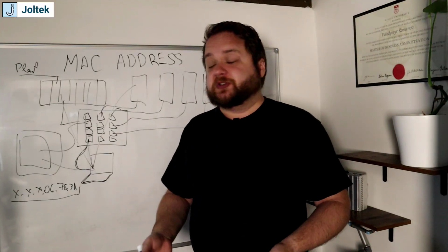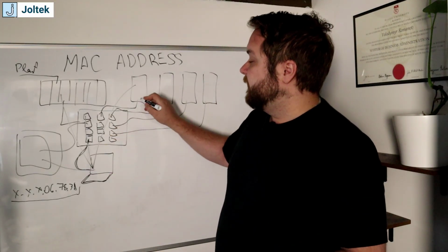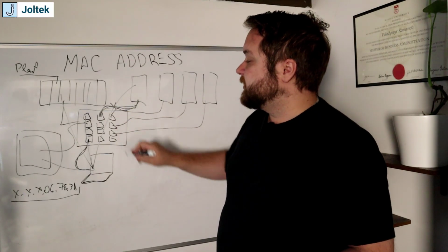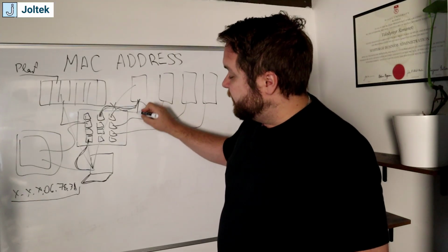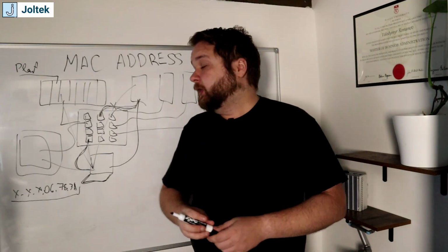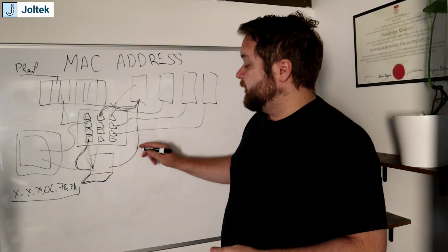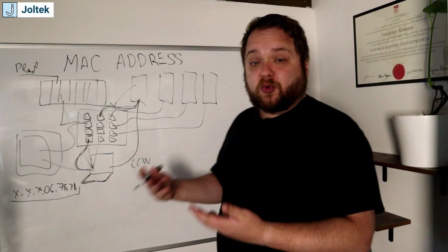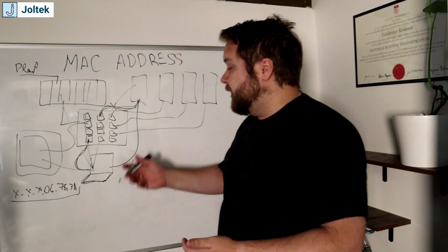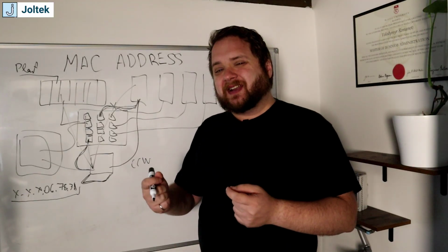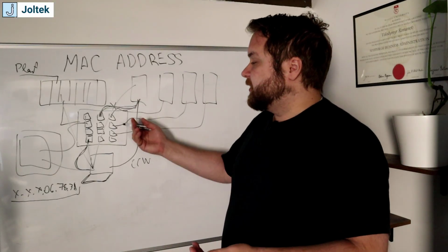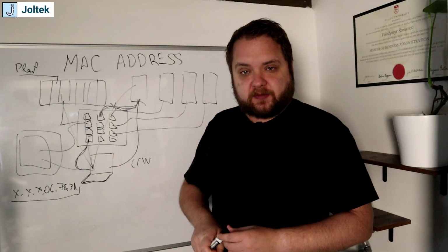The alternative, of course, is you can disconnect. So for example, if you have a VFD that's currently connected to the port of this Ethernet switch, you can simply disconnect this cable and connect directly from the VFD to your laptop, right? So just as we've done on the test bench, you can simply connect to that device via CCW, and you've basically prevented the issue of assigning the wrong parameters, the wrong IP address, to any other device. Now, of course, I say that with a caveat, right? In a commissioning type of environment, you can disconnect devices and connect to a specific device.